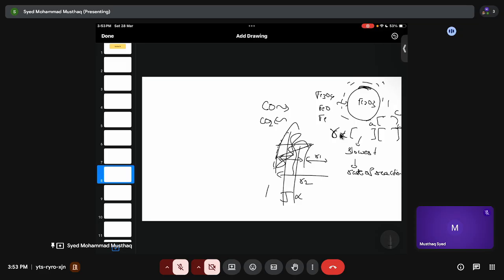And again, the DSR, the direct smelting process. In the direct smelting process, we do not use coking coal. We do not use coke. We use non-coking coal as a reducing agent, and that means we are completely avoiding the coking process. So all we need to do is ore preparation. Either you do the pellet or sinter. It depends upon you, which is more economically efficient.